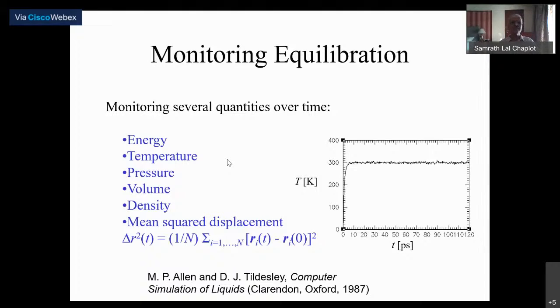But let's just see. If it's a simulation in which you hold the total energy constant by not supplying any energy from outside, you can also do a constant pressure simulation in which you maintain a pressure by changing the simulation shape and size, in which case you are obviously supplying energy from outside or taking energy out. So it's no more a constant energy simulation. You can have a constant volume simulation, fine, that is possible. So it can be constant volume and constant temperature. You can have a constant temperature simulation.